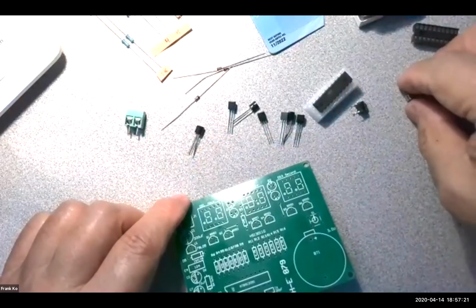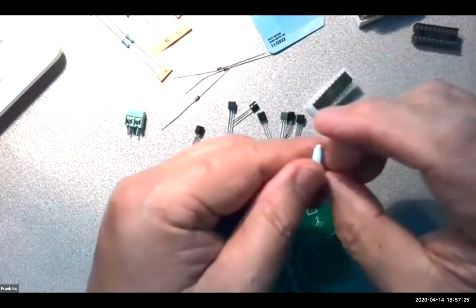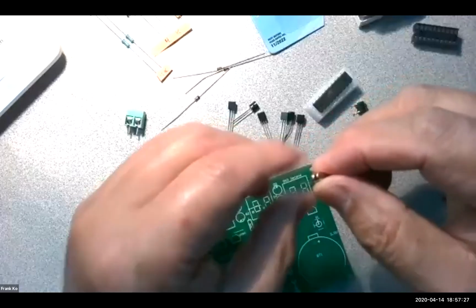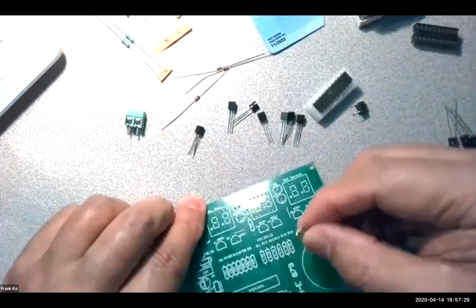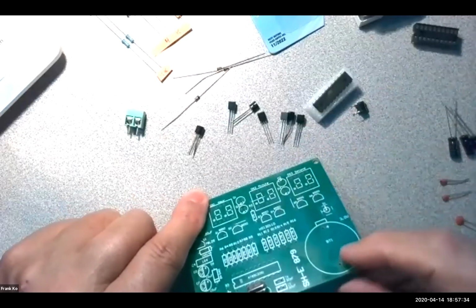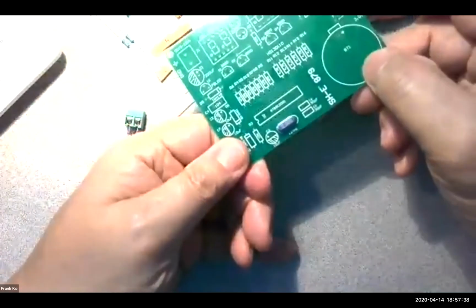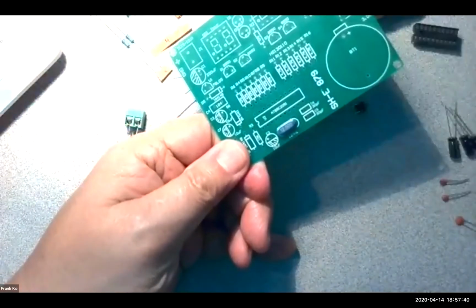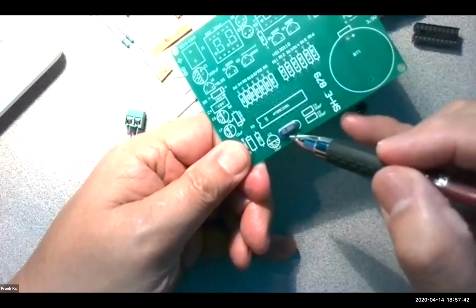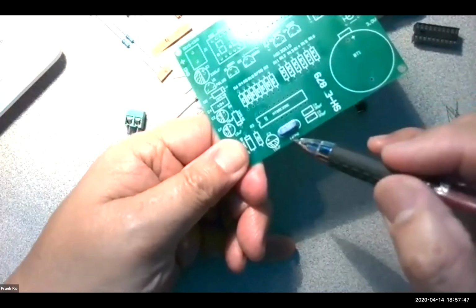Next is your crystal. This is for 12 megahertz, sorry. So this guy will go onto the board here where it says T1, because T stands for timer. And it'll go right down in there. And if we hold it up to the light just right, yes, you can make out 12.000 in the lettering. So keep that upright.